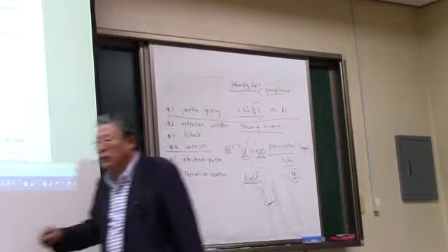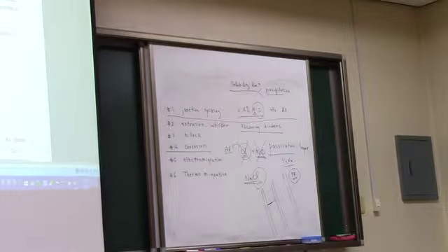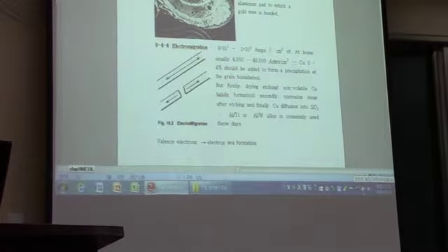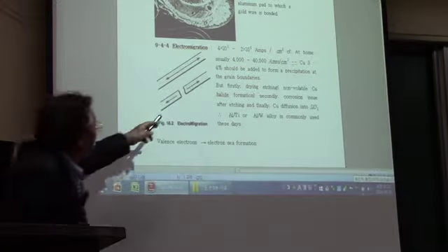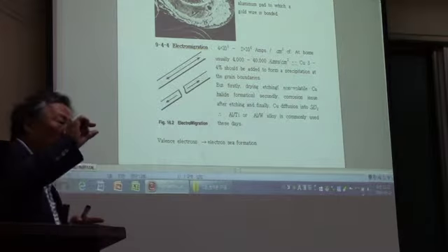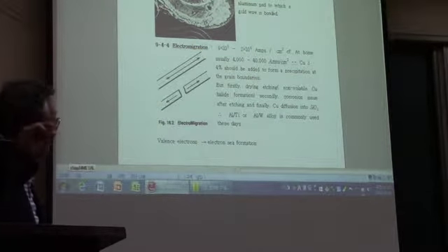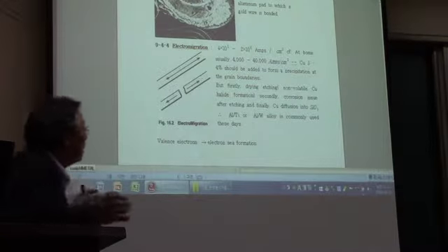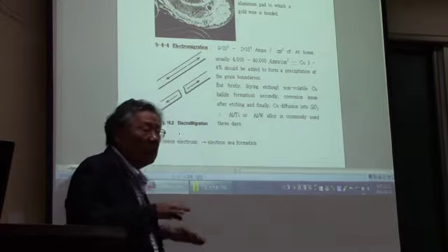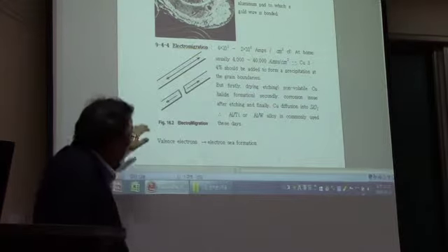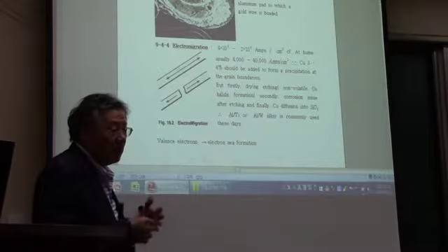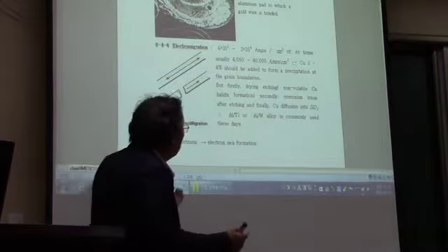Now, electromigration is a very important and serious problem in the metallization. In this explanation, you can see the metal lines are so narrow, and the thickness is on the angstrom scale, like 1,000 angstrom or something. So even though you are running a very small amount of current, since this line is very thin and narrow, it is going to show electron migration. What is electron migration?